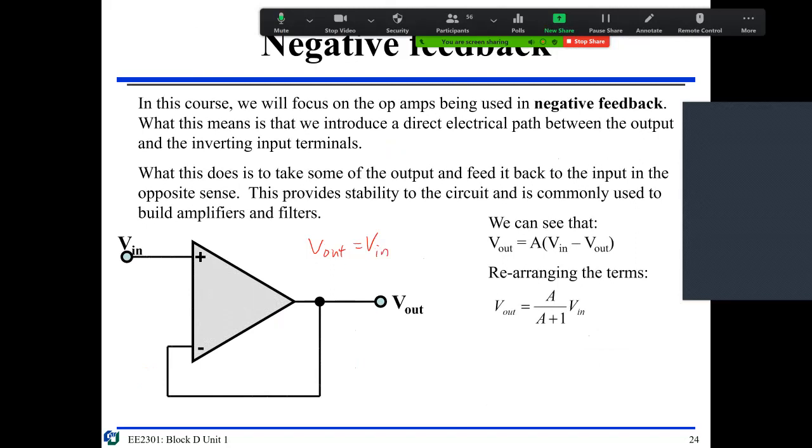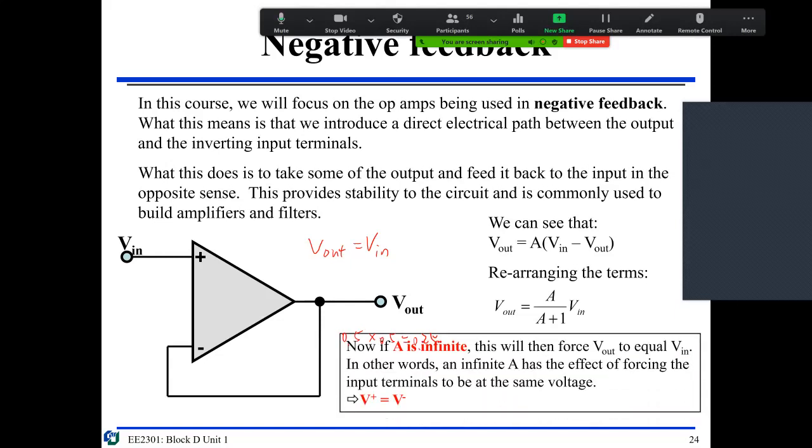People may ask, why bother doing that? In quiz number 2 last week, you wanted to cascade 0.5 with another 0.5, and 0.5 times 0.5 is 0.25. In between, you have to put something like this. This is called an op amp, so that you have the needed impedance matching. Because A is very, very big, the gain is very, very close to 1. That's called a voltage follower.